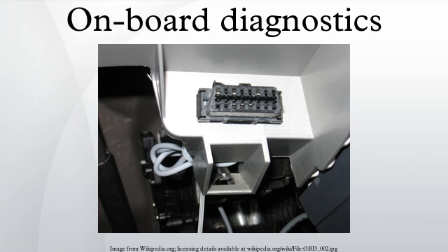Mode $8 could enable the off-board test device to control the operation of an onboard system, test, or component. Mode $9 is used to retrieve vehicle information.